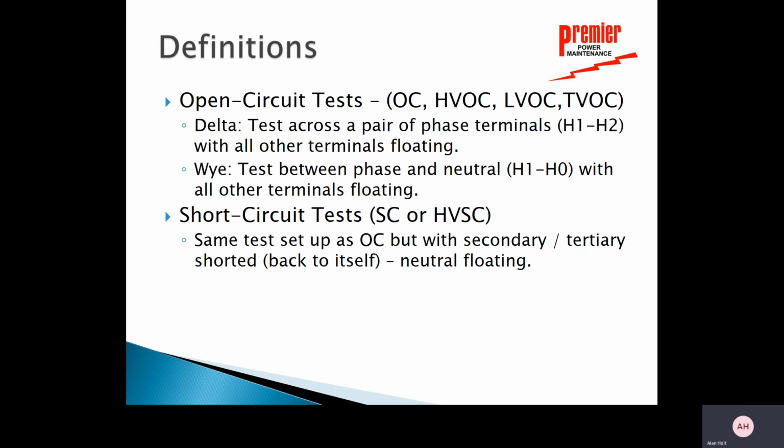So if you had a 3 winding transformer, you can see you're going to have 9 tests there before you do anything else. If you've got a delta connection on the high side or the low side, either one, you test across each pair of terminals, H1, H2, everything else floating. We already showed that on the diagram. On the Y winding, test between phase and neutral, H1 to HO, with everything else floating.